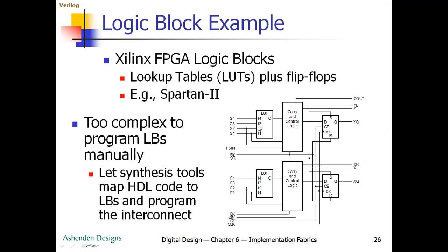The 4-bit data input can be the address of a 1-bit location of the LUT. The data stored in that 1-bit location is applied as the output, according to the address applied.